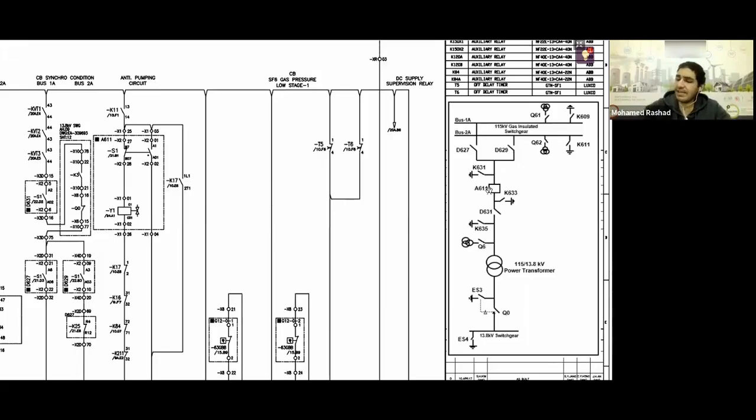When we explained the single line diagram of the double bus single breaker, we agreed on the concept that the disconnector and earth switch are things that do not open or close on loads. Only the circuit breaker opens and closes on its loads. So to close this circuit breaker to the on position, either you close it in the test position, meaning in the test mode because it is under maintenance, or you close it in the service position, meaning you now want to close it in the service mode and connect it to the electrical power. Okay, now if you want to close this breaker in the test position, what does that mean? It means you need to isolate your circuit breaker.